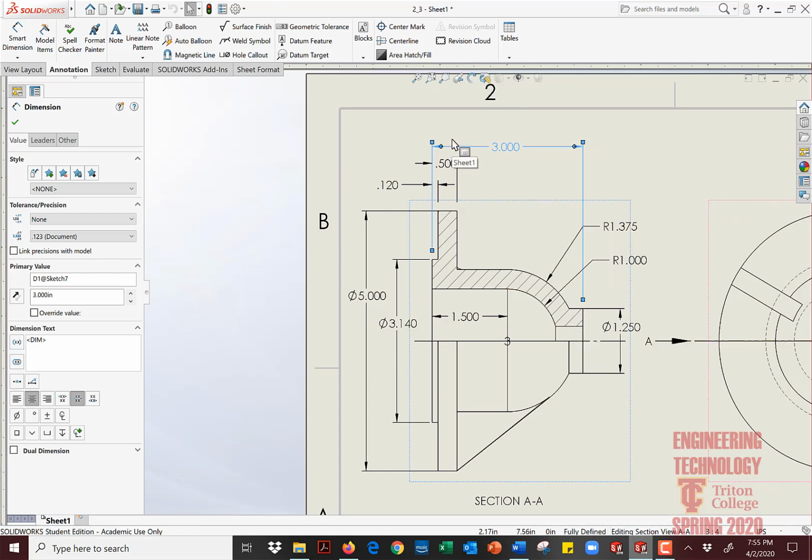That is the power of this software. Inventor does this, Solidworks does this, ProE does this. All of the 3D parametric model packages do this, if and only if you utilize the model dimensions in your detail drawing. If you manually dimension your detail drawing, you basically have a dumb drawing. You cannot manipulate the model from the detail drawing. Okay? So please keep that in mind.